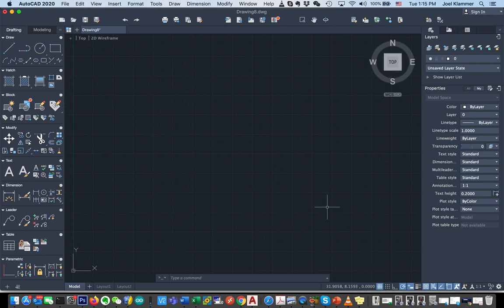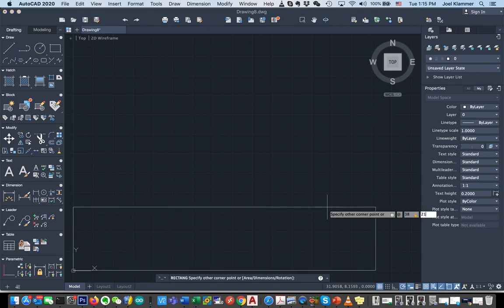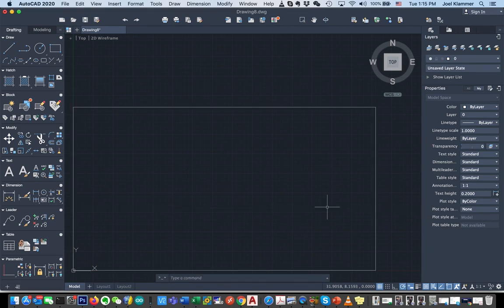All right. Now my main rectangle. I'm going to specify it using the @ sign. On your Apple keyboards, that's Shift 2. I'm going to say 0, comma 0 is the first insertion point. Press Enter. And then for my other corner, using again the @ symbol, I want it 38 wide, comma 21 deep. And so here it is. Here is the outline then of my house footprint.